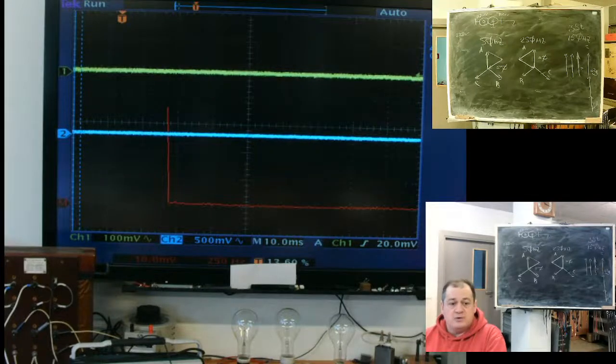Okay, I think it's enough for today. The key moment is the idea that some harmonic components rotate directly, some are symmetrical in phase but have an opposite phase sequence, so at this frequency the magnetic field in a machine rotates in the opposite direction. And some act like a zero sequence, so they are equal in all phases. It's important to remember.